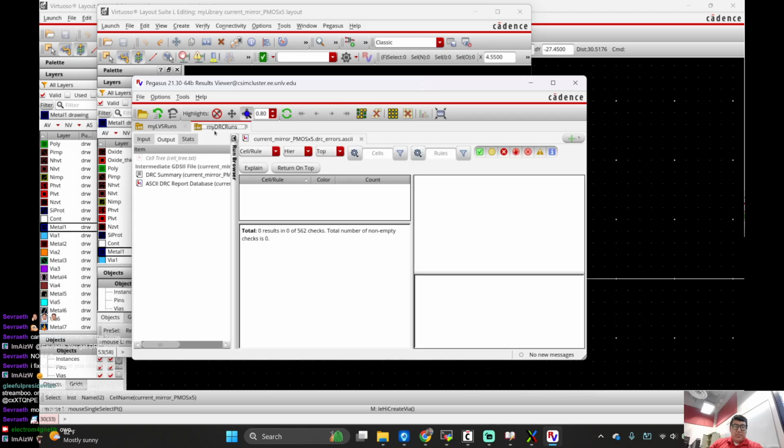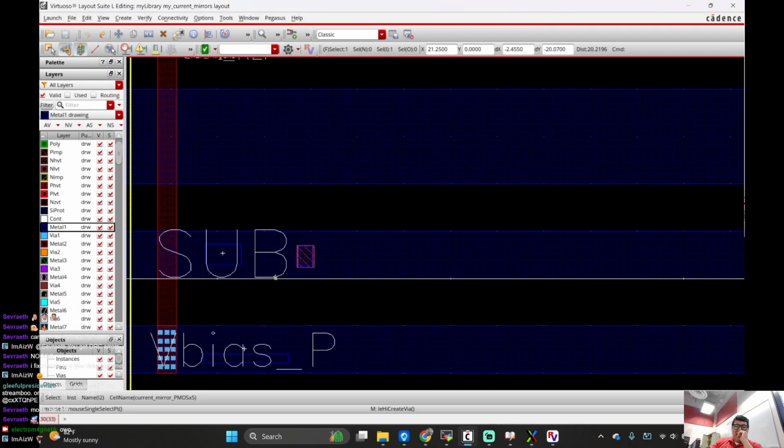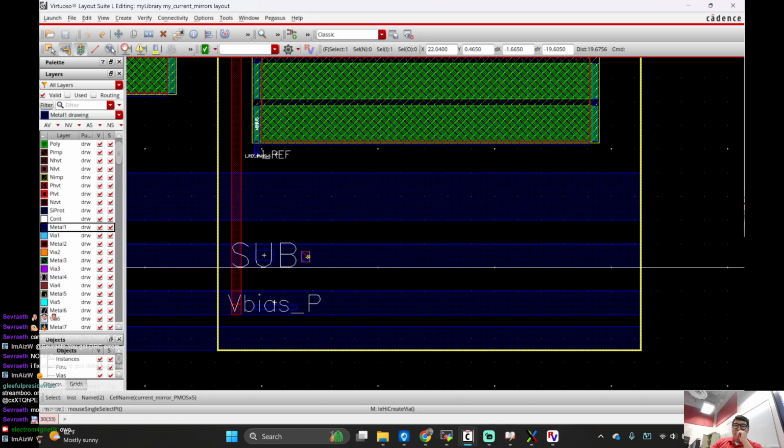My LVS runs. Here's my DRC run, and you see it fixed it right there, right? Let me show you that I ran the PMOS. You see current mirror PMOS 5, right? The DRC fix. Remember that bonus question from lab 2? How do you solve that problem? Just put metal 1 to the P sub. That's the answer, okay? A few of you did that. I'm shocked that a lot of people didn't do it. But yeah, that's how you fix that problem.